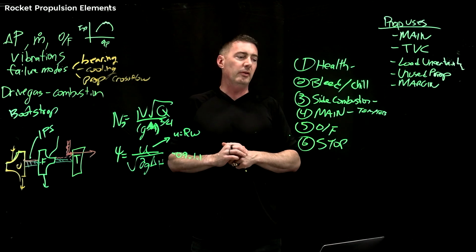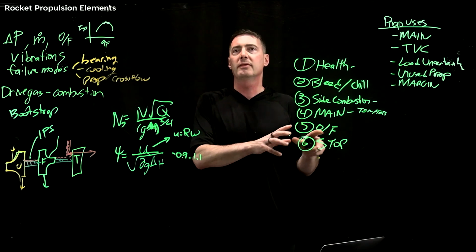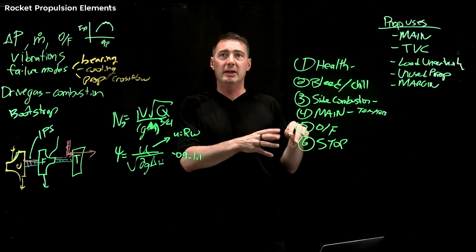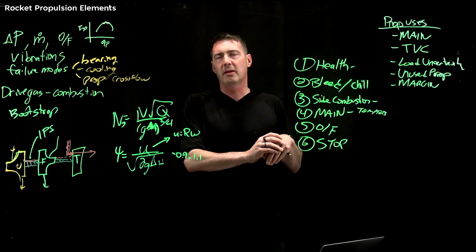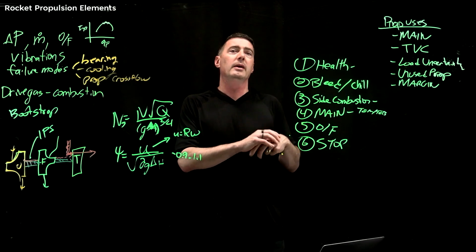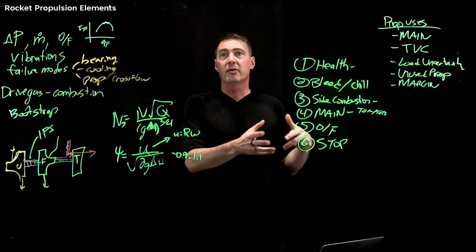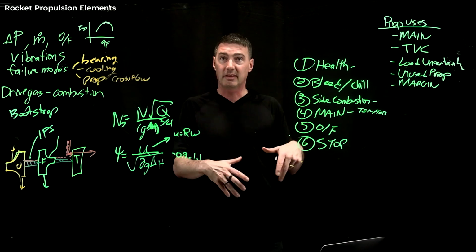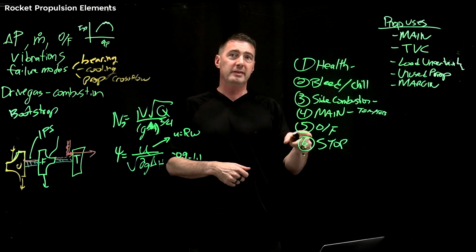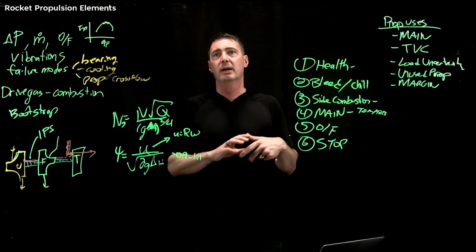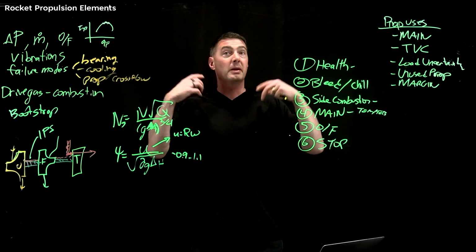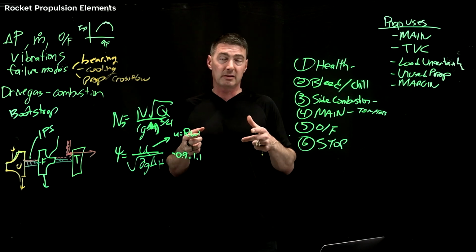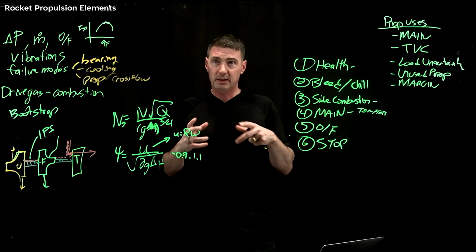And now you may say, I don't care if it's destructive. Yes, in flight, once your engine stops, destructive can mean lots of different things. So you don't want to blow up, but if stopping your engine in a way hurts the engine, you could be like, well, I'm not using it again, unless you're trying to reuse it, like SpaceX will land it. But no, it's actually the fact that when you build an engine, usually you're designing it for an expendable rocket. You're still going to design the engine for 20 starts, because it may take 10 starts for you to prove it out and tweak it on the test stand.